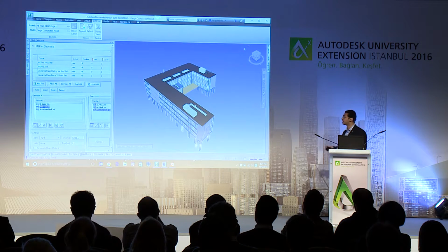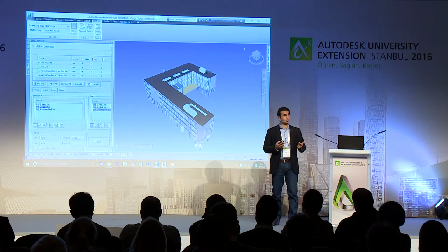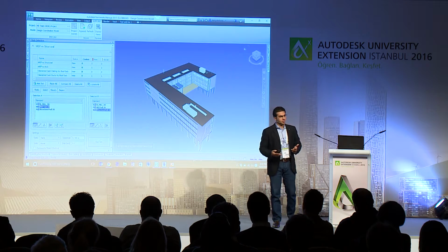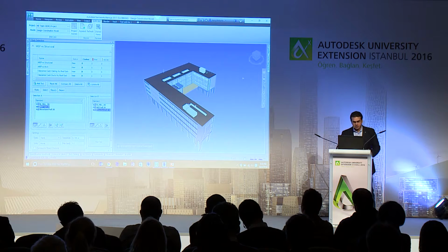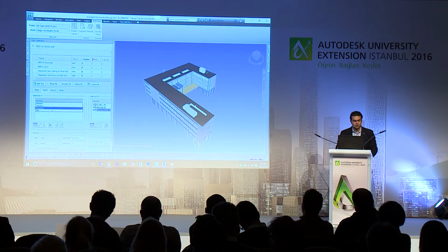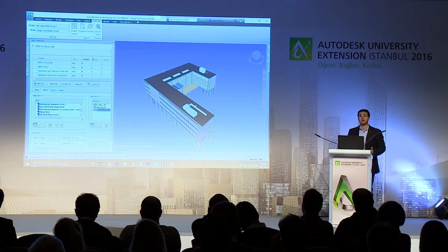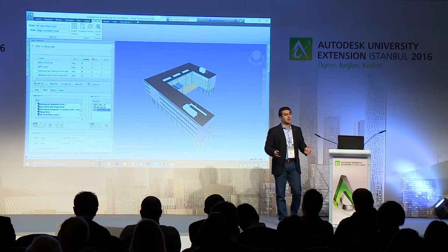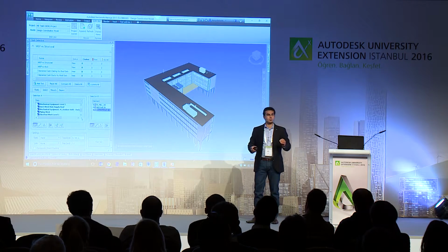The main differentiator inside Navisworks is two things: first, the flexibility to select the model objects to perform the clash detection or design coordination, and second, the extra types of clashes that can be performed. What does it mean? Let me do it here by example. I have here a clearance clash test. Before I talk about it, let's look at the ability to use search sets to classify my model and select objects no matter where they reside in my BIM model. I can use the properties in my project to filter certain objects and find them.